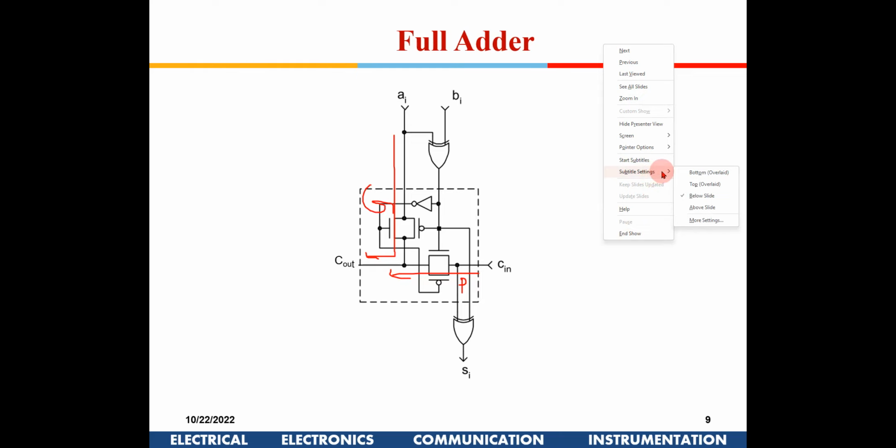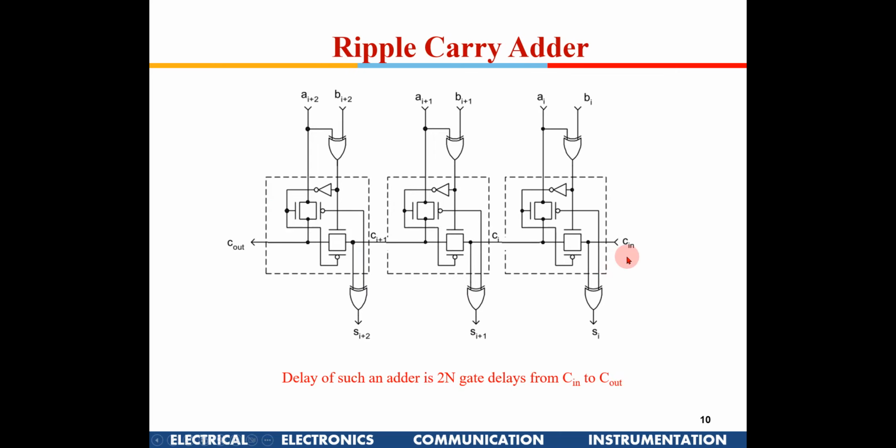So this is a full adder circuit, and then obviously you have the propagate and the C in XOR gate to generate the sum also. So this is one, right? Now when I have a ripple carry adder, I have one full adder, the carry is taken out here. It is being driven and is given as an input to the second full adder.